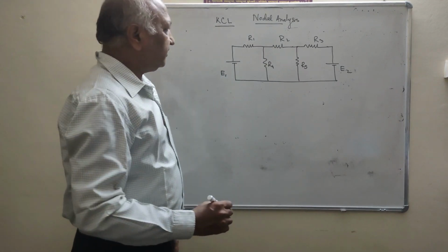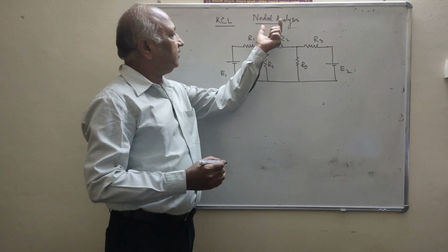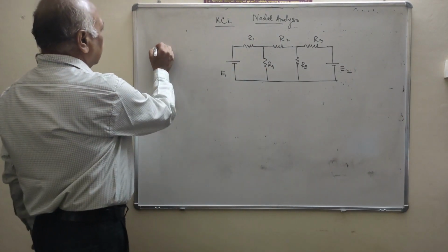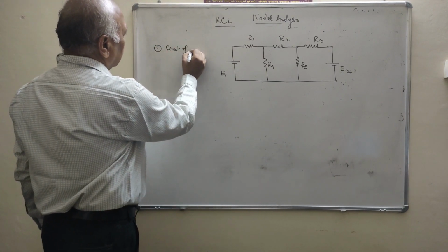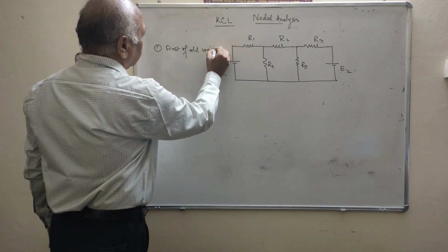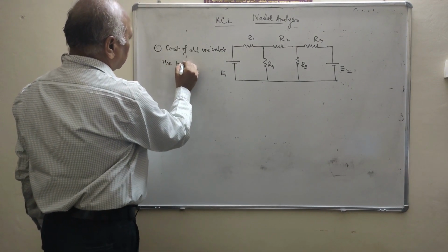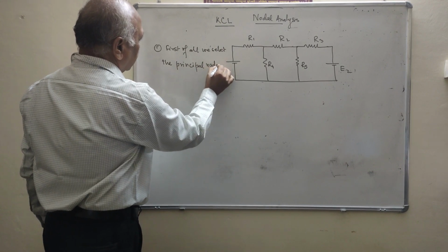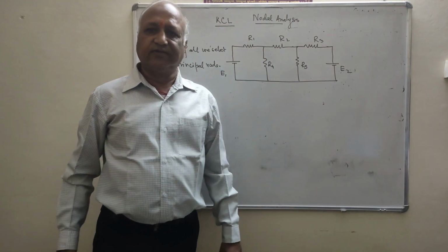Clear? There are a few steps which are followed in nodal analysis. First of all, we select the principal node, a node where three or more branches meet.